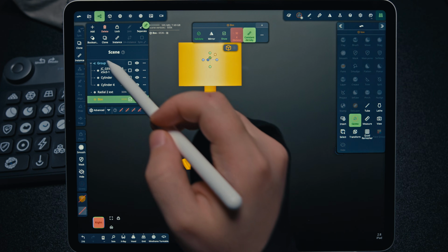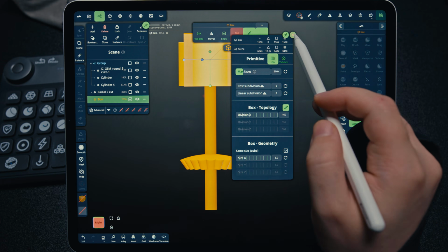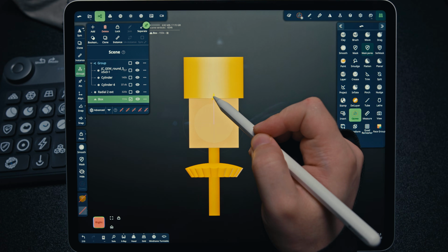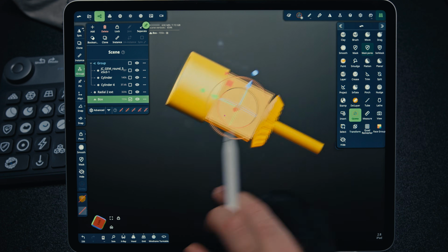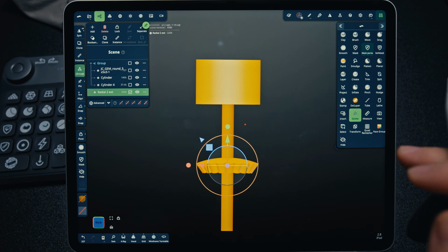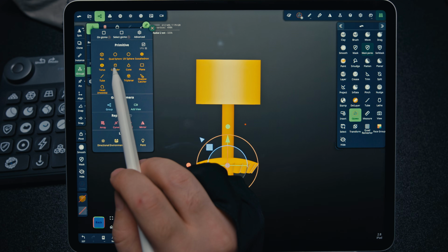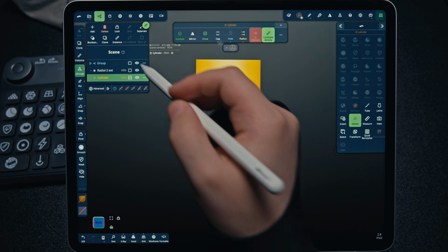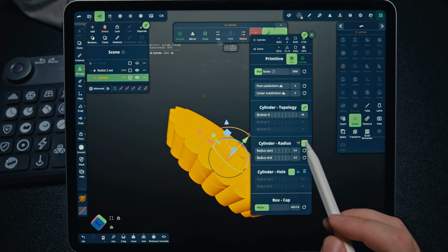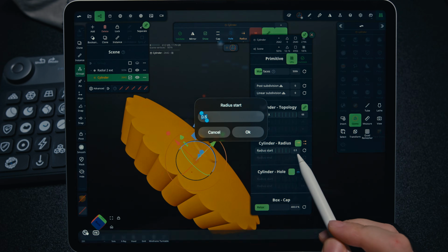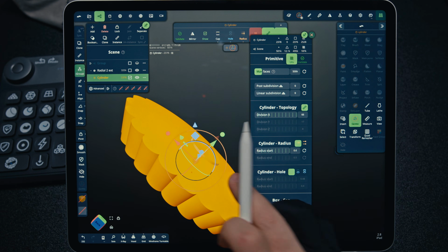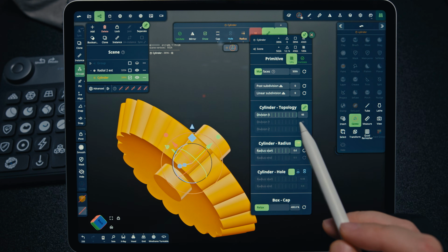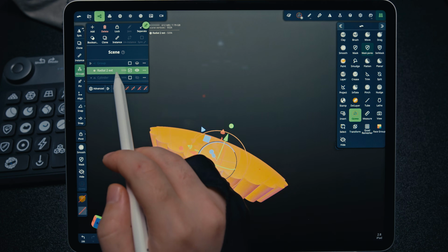I'll add a 5 mm reference cube to the scene. This will be our earlobe. I'll raise our pie higher, guiding by the cube. Now the cube can be deleted. Moving on, I will add a new cylinder. With it, I will make a pilot hole. For our post to fit through, we need to make this hole with a 0.6 mm radius. I'll make it a bit longer and boolean it out.